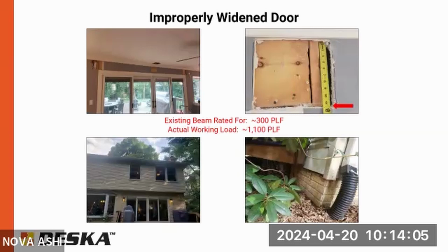So again, luckily wood is very forgiving. It's a very serious problem, but luckily it just needed to be fixed, and it gave the warning signs that something was going on, and the homeowner noticed and did the right thing. In addition, whoever installed this 12-foot wide opening installed one of the columns right above a window well, or a basement window in the basement, which was not properly rated for that. They just installed it right on top of the window. So that could have been much worse.